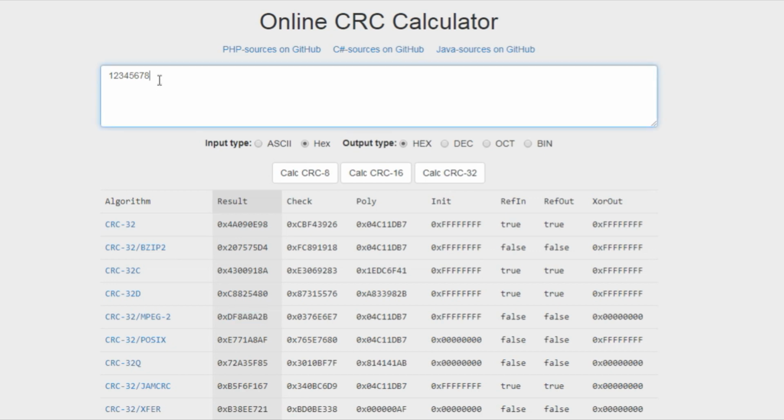So we'll do another one. I'll erase the input, and I'll put in 1, 1, 2, 2, 3, 3, 4, 4. And we'll do a checksum. If we look down, there's our CRC checksum for those 4 bytes: B14257CC. So you just remember those two, and then when we do our calculation on the ARM microcontroller, we'll see if it matches these CRC checksums.